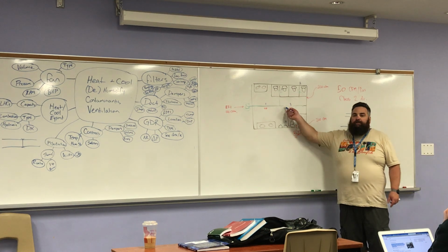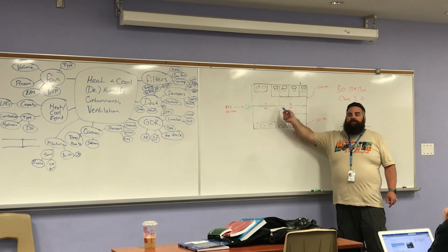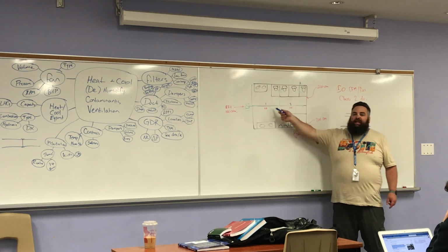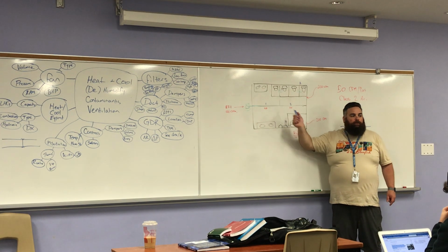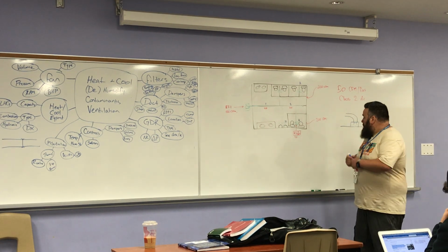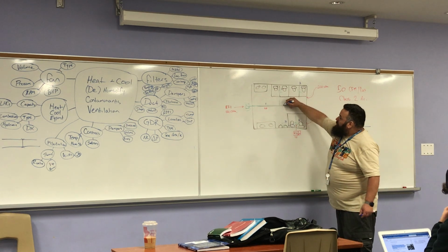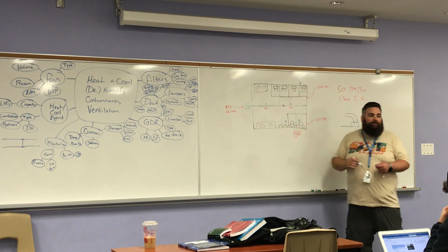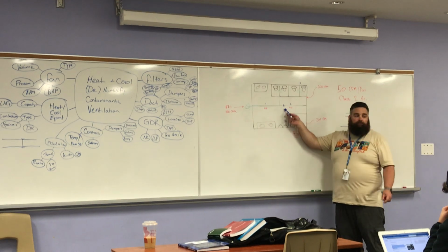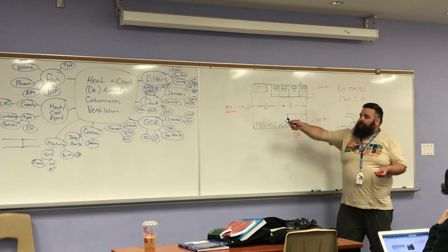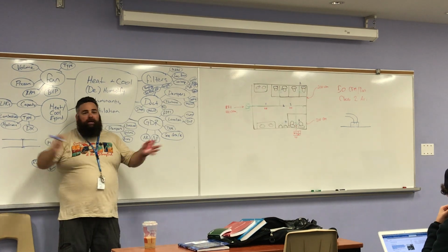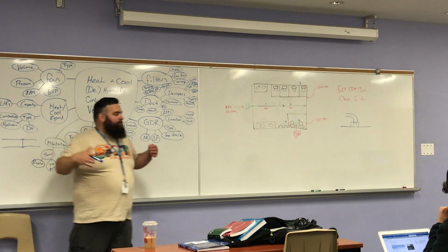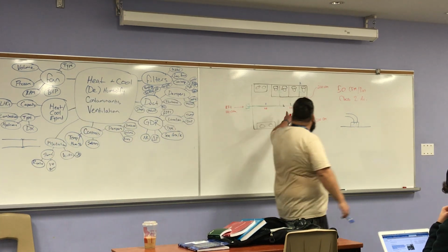There's one thing I didn't show here, but we discussed that you might be able to infer it. We have a change in size, don't we, between trunk 1 and trunk 2. So I've got a transition fitting. So I'm going to draw a triangle here to show that I get smaller. That's another fitting. Okay? Remember I told you about the delta? That's the same thing in that fitting, right? The duct got bigger, so the air slows down. Okay? So we have a pressure drop there.